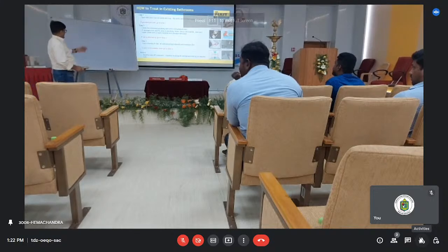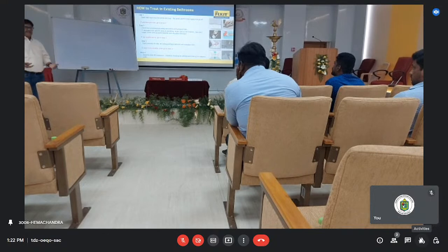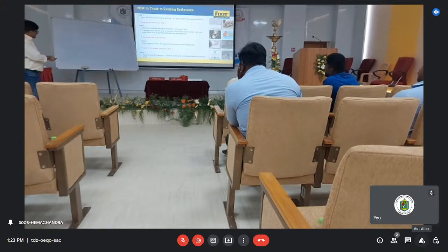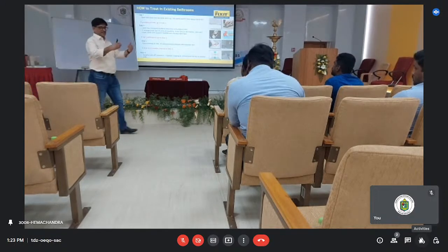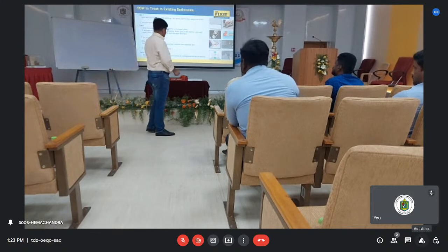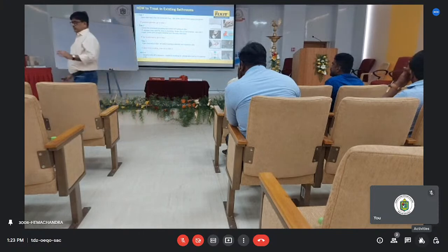So if that is confirmatory, if that is the joint, do that. Upon removal of the joint, do the repair. If that is also not happening, then you have to remove the tiles and do the waterproofing treatment, the positive side, as Ashwati has told. And if that is also not working, if it is not at all possible to do it, then come to your injection system. You should not go to the injection system first at all.